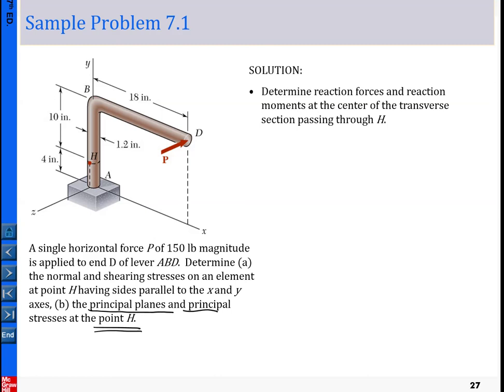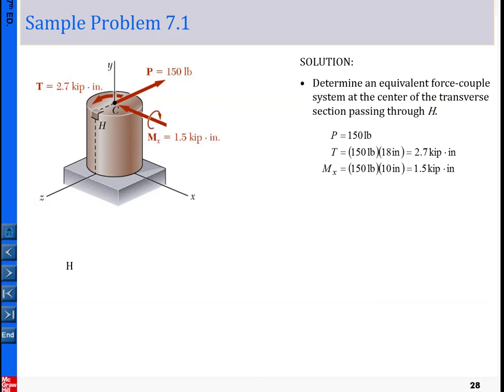At the very first step, we need to determine the components of the stress here. So here we simply apply the combined loading. In terms of the coordinate systems, here we define the x, y, z like this one here. That means we pick a stress element, something like this one showing here. Let me highlight this stress element. That is the stress element we're going to demonstrate.